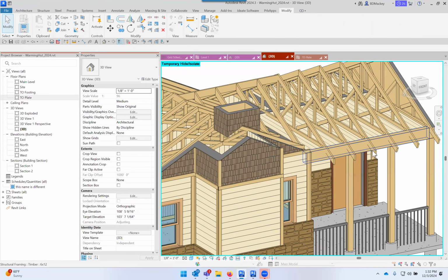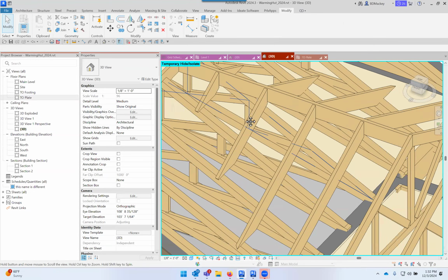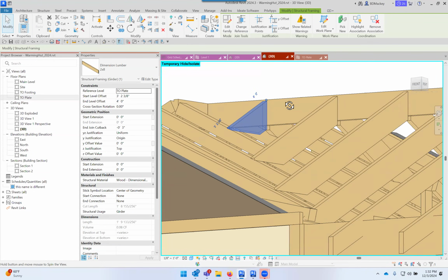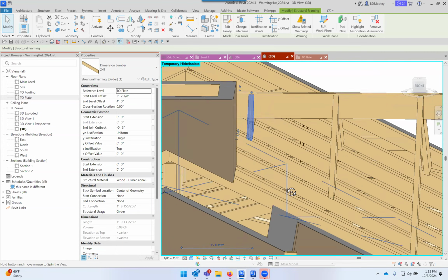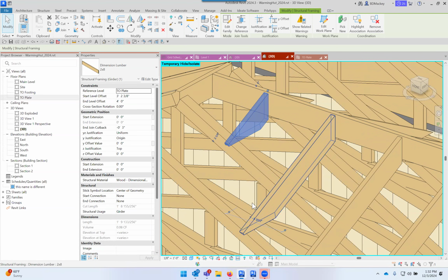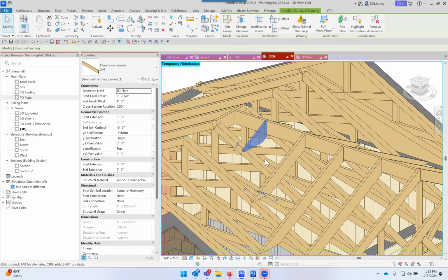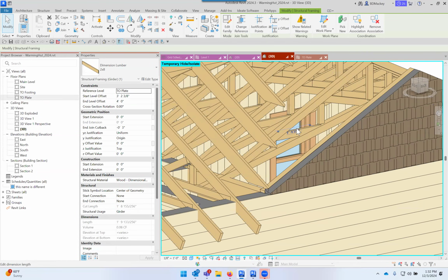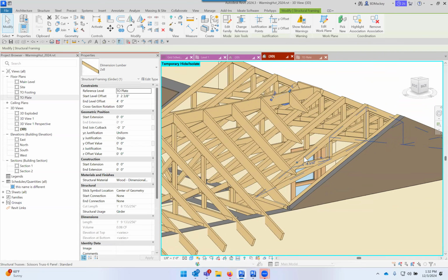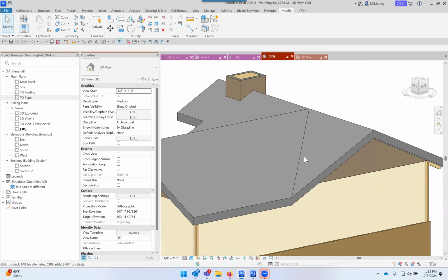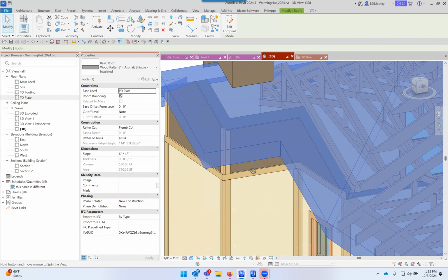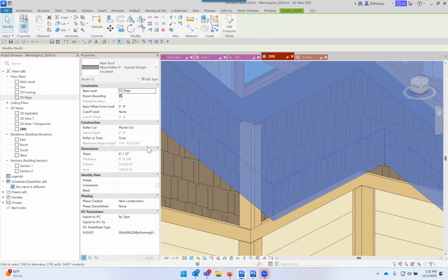If you really want to have fun with that on the structural tools, you can draw a reference plane in at the compound angle. So yes, I drew a reference plane in at the angle of this roof, and then I could use that to cut all of these to get my compound angle. So it is possible. Again, I did those with a reference plane. I'm not saying it's something anybody would ever do in reality. It was just something I was going to show. But architecturally, if you just don't want this roof to be plumb down here, that's what this rafter cut is for.